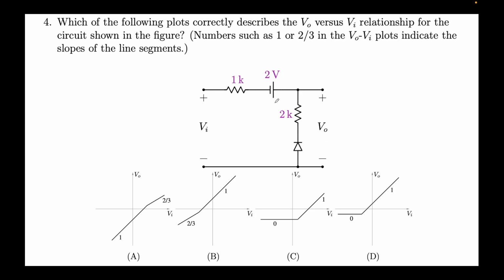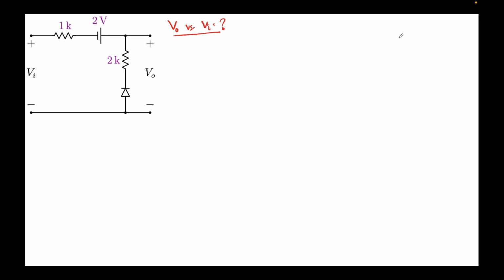Again, compared to the previous question, just the voltage source polarity has been reversed. And as usual, I'll simply put, this is the model that we are using, ID versus VD. Again, V on equal to 0.7 volts, and as we did earlier, case 1, when VD is greater than V on.